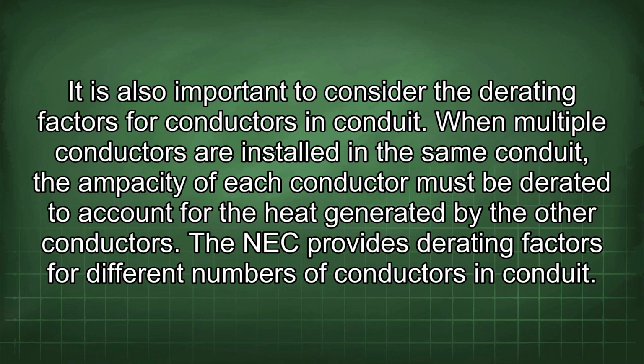It is also important to consider the derating factors for conductors in conduit. When multiple conductors are installed in the same conduit, the ampacity of each conductor must be derated to account for the heat generated by the other conductors. The NEC provides derating factors for different numbers of conductors in conduit.